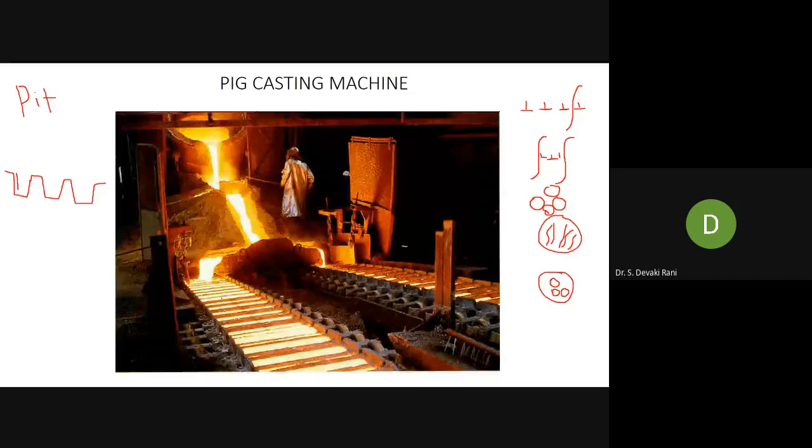Okay, come back to this one. So pig iron, when pig iron goes to the steel making shop, you get steel. Pig iron goes to the foundries, to the cupola, to get cast iron. From the cast iron you can go for malleabilization treatment to get malleable cast iron, that is 100 hours heat treatment makes malleable cast iron. The same cast iron, if you remelt it and add inoculant sodium, cerium etc., you get gray cast iron. Or if you take the pig iron and heat it in a reverberatory furnace, you get wrought iron.